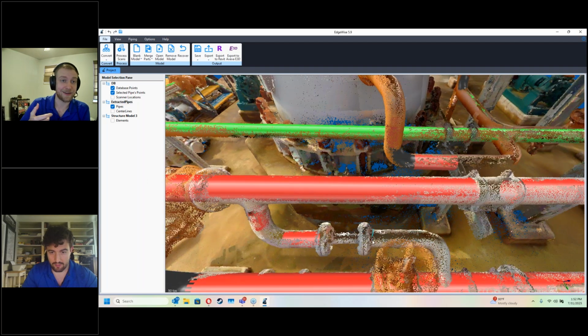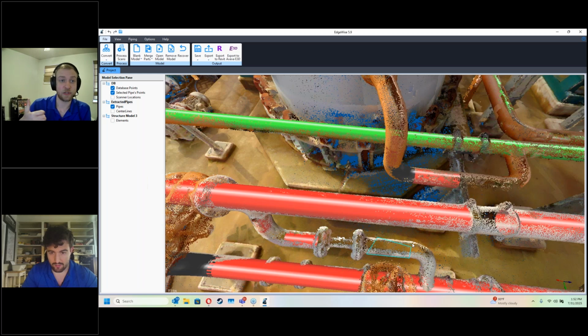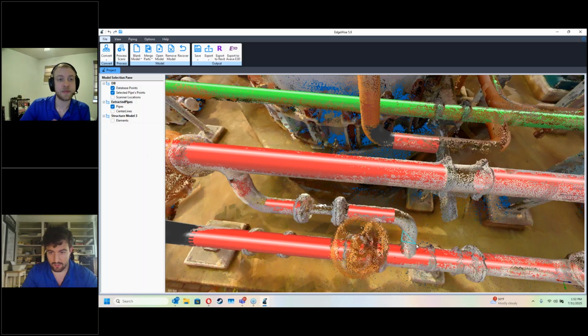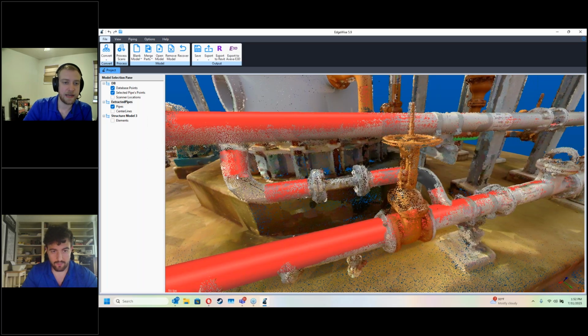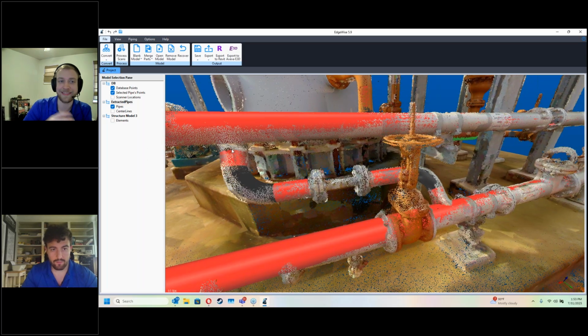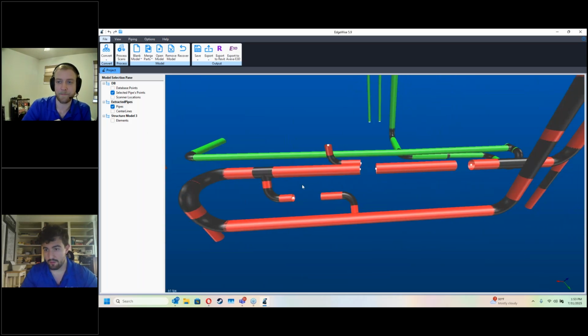We do recommend using layer and level naming inside of the chain info smart sheet, because that name will show up inside of Revit as the Revit family name of that generic pipe. So if you want to add details that you want to remind yourself of later inside of Revit, you can put that layer level information in the chain info smart sheet, and then that will show up. That information does translate through E3D as well.